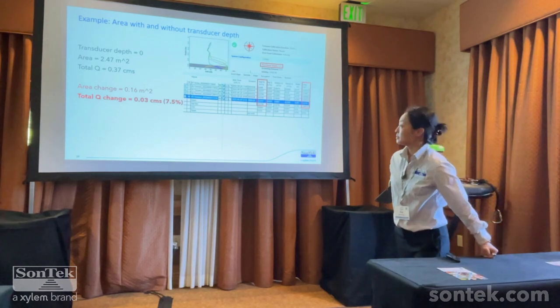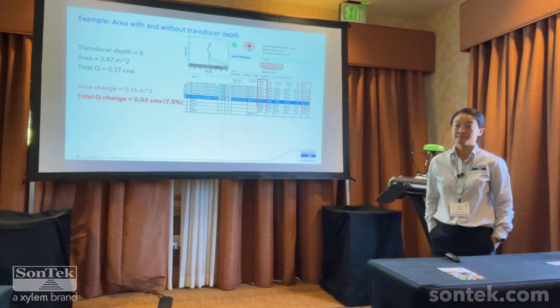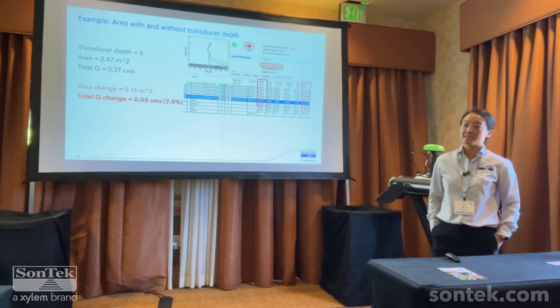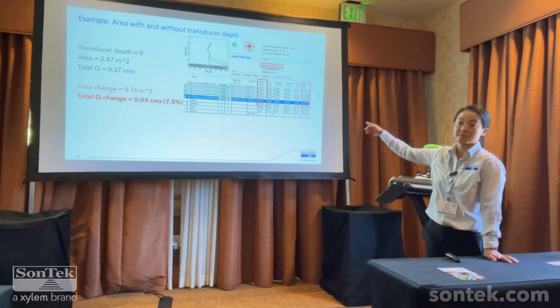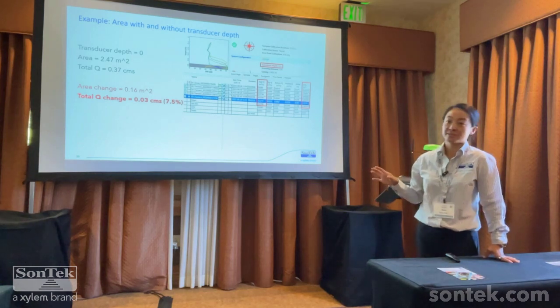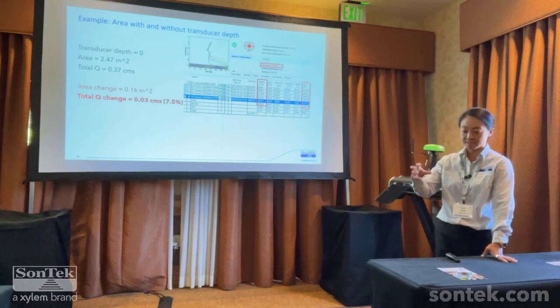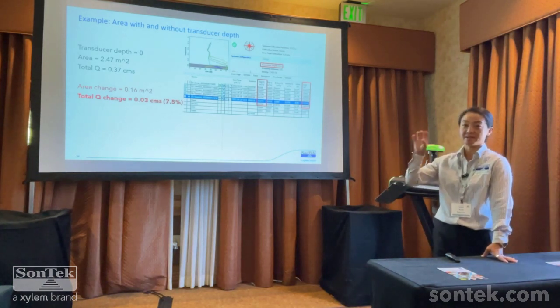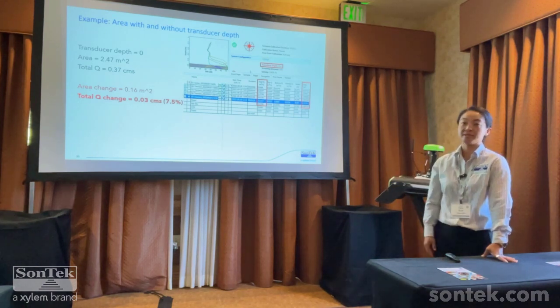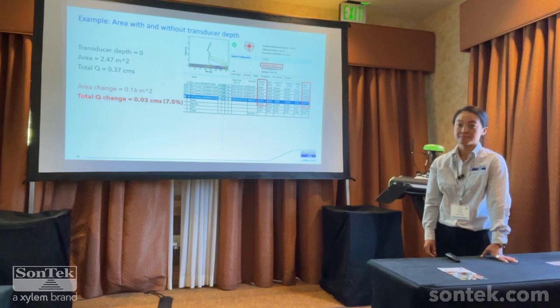And do you need HYPACK to get the bottom elevation out of it, or can you get the bottom elevation? You don't necessarily need it. You can export all of this data, and the MATLAB export is what goes into QRev, and that's all the raw data, so you can manipulate that however you want. HYPACK just gives you an easier way to visualize the data, the lat-lon, and then the actual soundings. But if you have people who can process that manually, you can get a sense of what the bottom looks like, so you can put that in your other graphic. Yep, you can do that pretty easily.